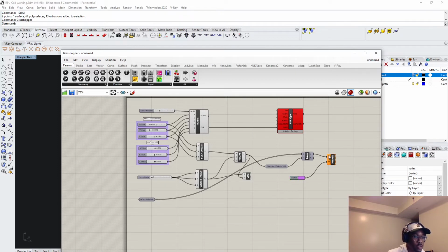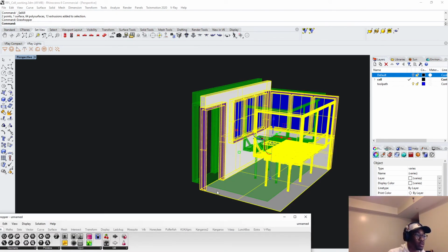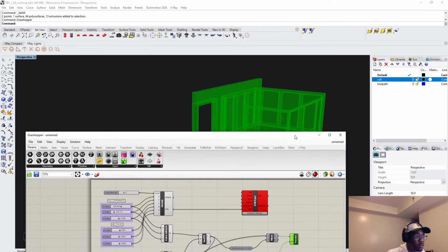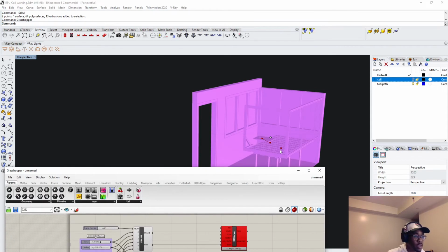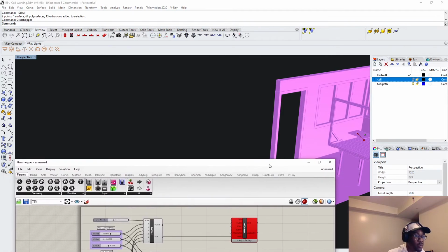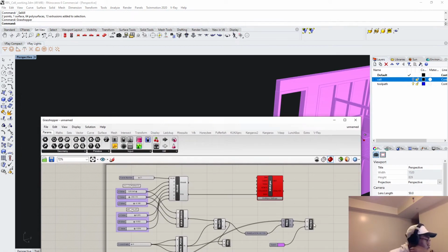Give it the swatch color. Give it the geometry. Now we can preview our moved geometry, and we can actually hide our cell. So put default back on as our working layer, turn that off, and we deselect. We now have our cell. It's purple. It's in Grasshopper, and we can move it parametrically if need be.